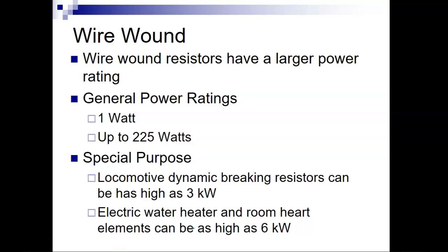The most impressive ones I've come across are not very high in the resistance rating, but they are very high in the wattage rating. You can get kilowatt ratings on things like overhead cranes, because to start those motors up and then to start up the braking mechanism, you have to pull a lot of power. I have seen resistors seriously boxed in, and they're taller than me. Yep, they come that way.